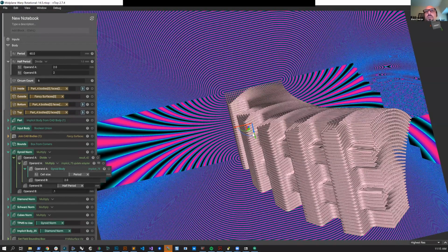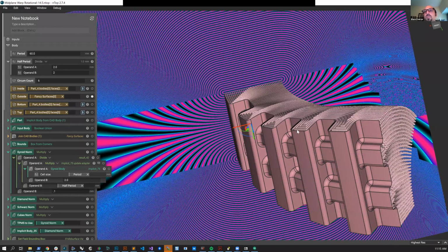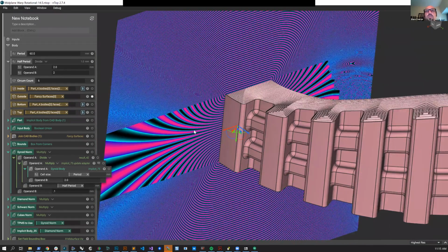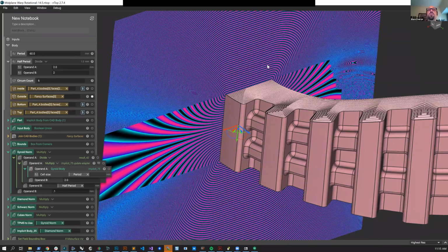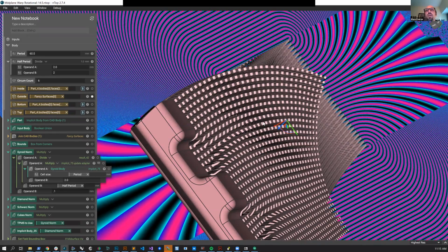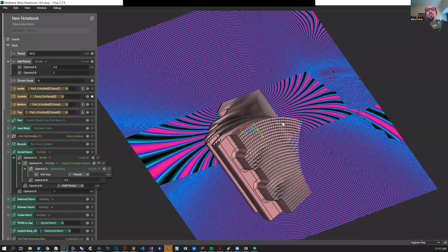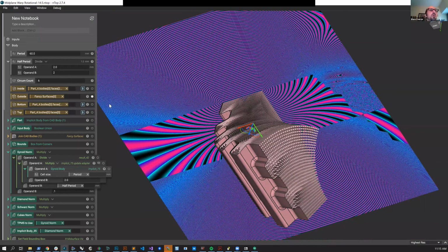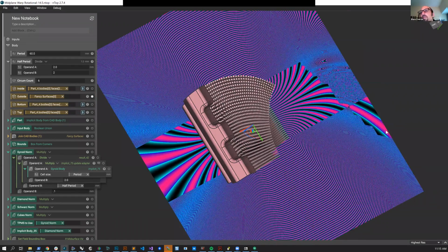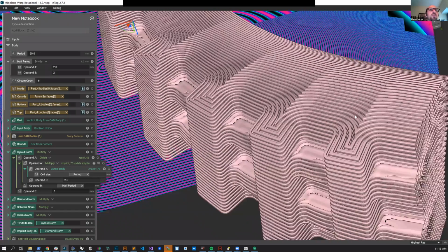Like these guys. These could be overlapping and a lot nastier, frankly. But we can take this as one of the sides of our two-body field, as well as another face over there. And you can see we create this gorgeous parameterization. And then around the thing, instead of using a two-body field, we're actually using cylindrical coordinates. You can create these different fields using a combination of distance fields and these two-body fields and other convenient fields to create all these amazing different remappings. And then you get these gorgeous flow lines. These are not streamlines, these are distance field lines, but quite useful, also useful for other kinds of manufacturing processes.